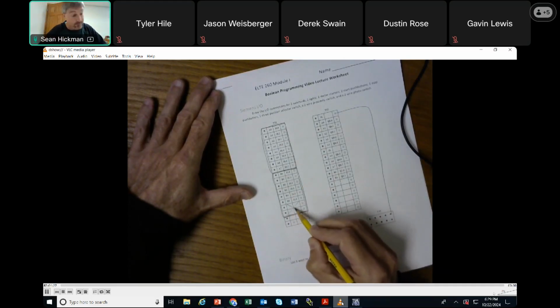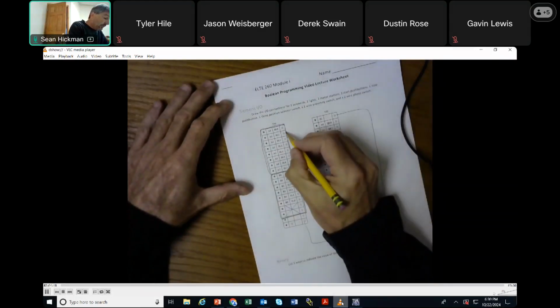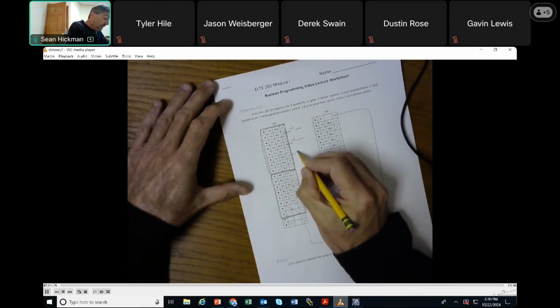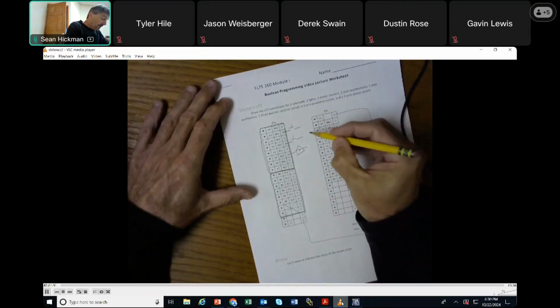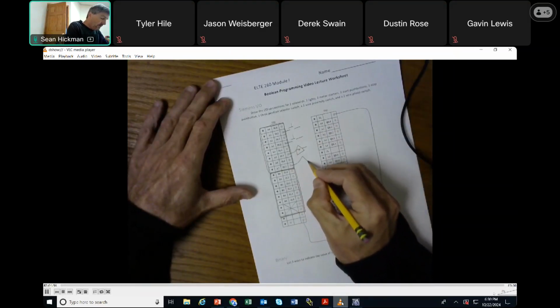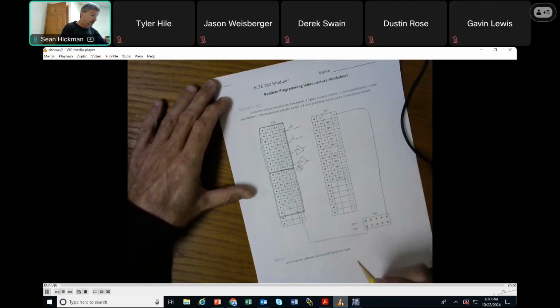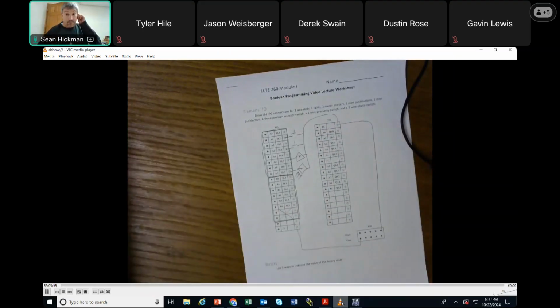That would be my full word, but it's not full. We do not complete that byte. Even though it's grouped in 8s, we're not using the last ones. And so when it says a couple of push buttons or whatever, you're going to throw those onto here. I don't even know what I got, a 2-wire prox. You wanted to put a 2-wire prox on here, whatever you're putting on there, right? A 2-wire photo, by the way, might look something like this with arrows on it. That might be that there's a wave there. And once again, these would all be coming back to my common. All right. Same as what we did for the sink, essentially.